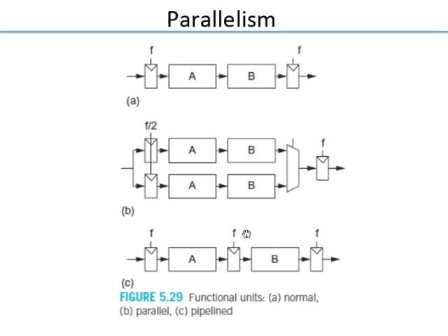So there is an overhead involved, and that overhead adds to the cost of parallelism. The gain should be higher than the cost. And as you push the throughput, the gains become quite significant, and so it becomes better to go parallel, either spatial or temporal or both, spatio-temporal parallelism.